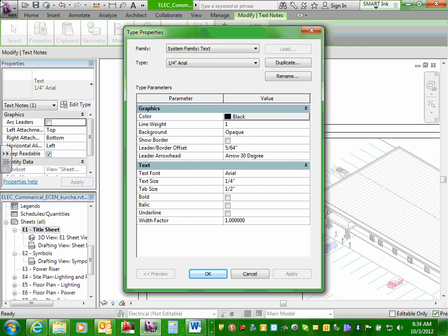Now we're editing. Aaron, my friend, when you edit things, the first thing you need to do is to duplicate it. Why? Especially text, because you could be using the same text in another sheet. If you edit the same text, guess what's going to happen to the other sheet? It screws it up. You can't believe how many times students come and say, Chad, I swear I didn't change it here, and it changed.